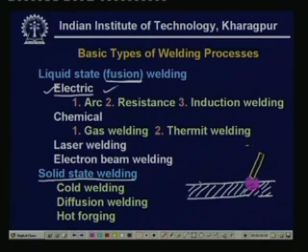Here, of course, the molten metal gets deposited. This is the weld metal, and on top of it there is another layer made of slag. This is the part known as slag. After the welding is finished, the slag is removed by various processes like chipping or grinding. The most important thing here is the generation of the arc.